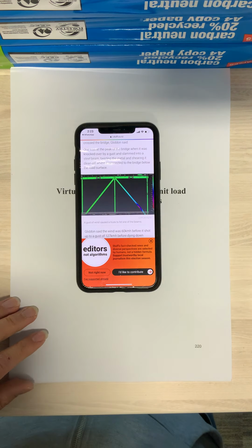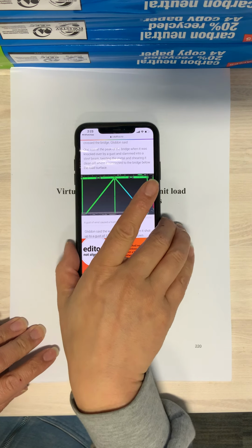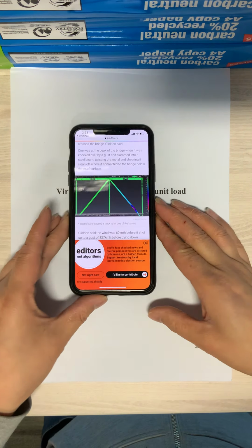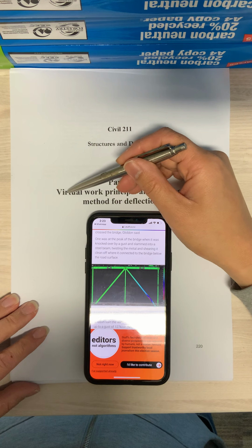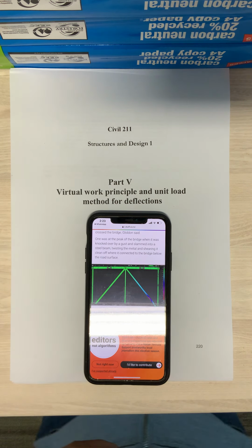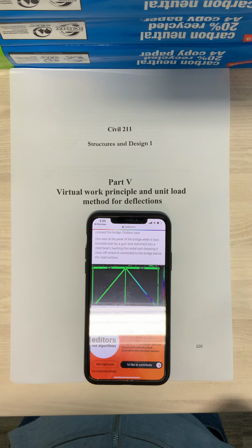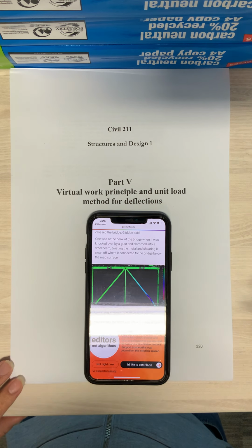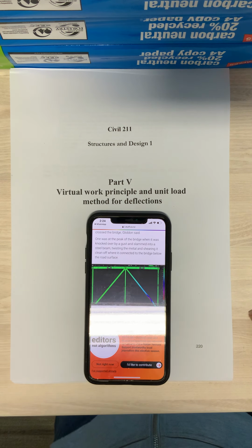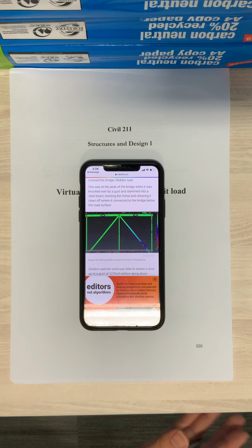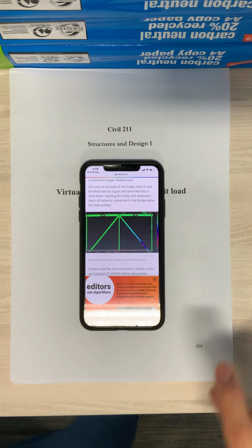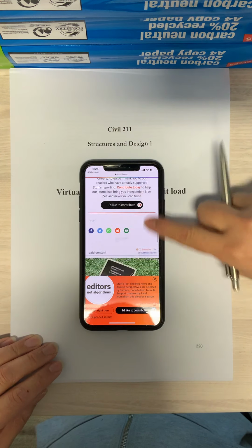The reason why I show this is that the compatibility equations and everything within the finite element model have actually been derived. If you check textbooks, you would see that they were derived using the principle of virtual work to ensure compatibility. Whilst you might not feel that you'll be using it in practice, the equations derived from virtual work can be seen in almost all the software packages that you would be using as a structural engineer. So let's move on from there.